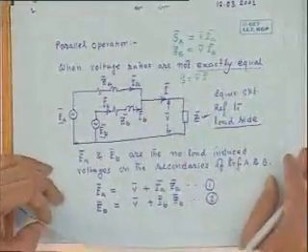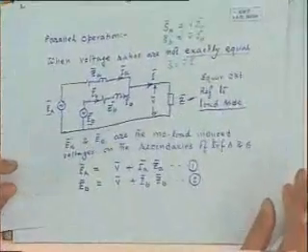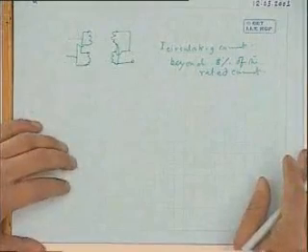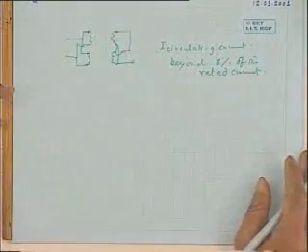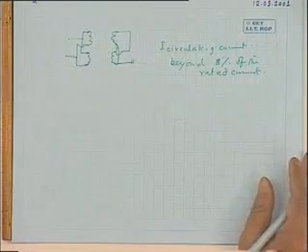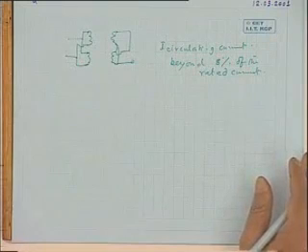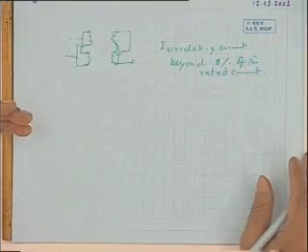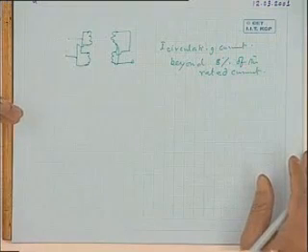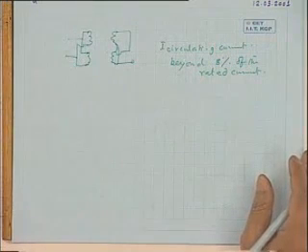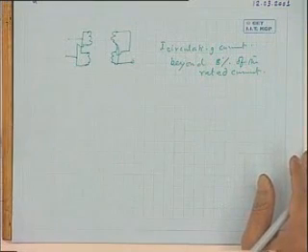Okay. And another important thing you should remember, that it is of course not a must condition, but one should see that the qualities of the impedances of the transformers are same, in order that they will be operating at the same power factor, such that the algebraic sum of the KVAs really become the actual KVA output of the transformer.